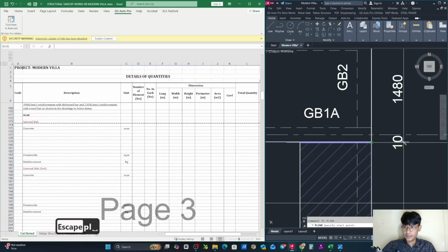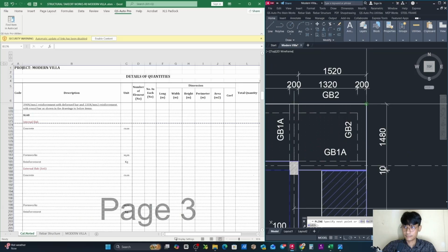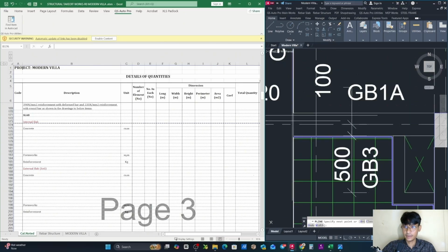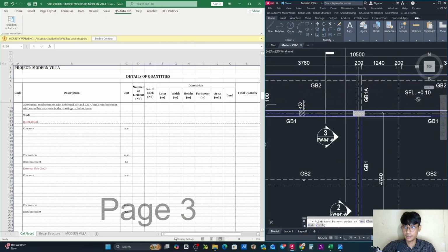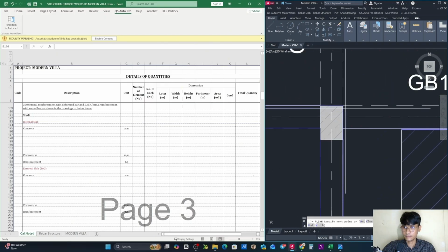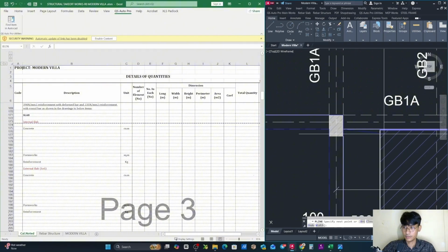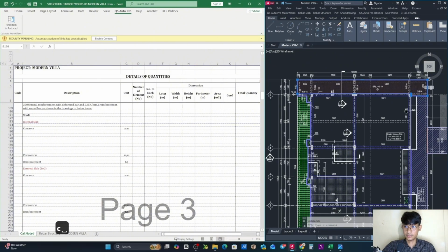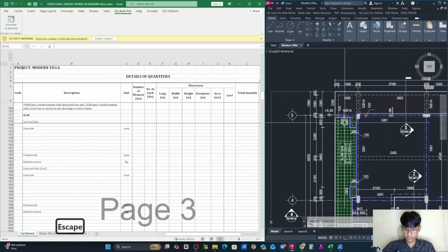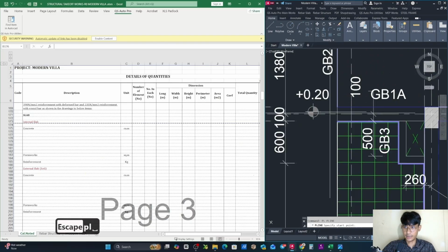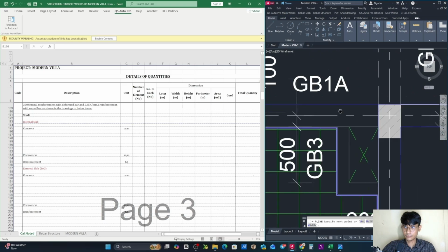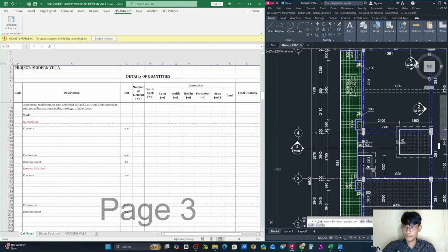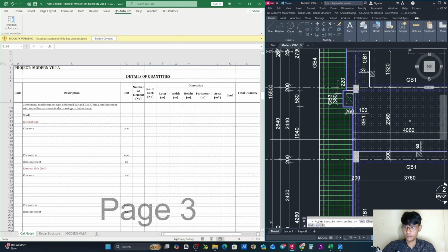Now we use PL again. Perfect. Here. And here. And C, enter to close the area. You can see. We do the same with PL for another area. Okay, let me take full with this side.